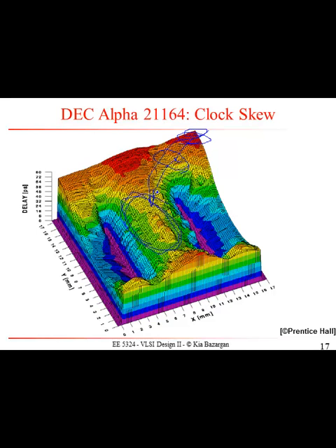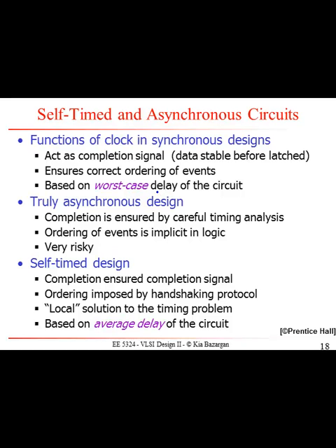So the important point is that within one clock cycle, the neighboring units that exchange data have to have low skew. But if over multiple cycles you fetch the data from cache, send it to the cache controller, and then in the next cycle send it to a register, and in the next cycle from register to your adder, the cumulative skew between these could be really bad. But if consecutive cycles are okay, then the chip is going to work.